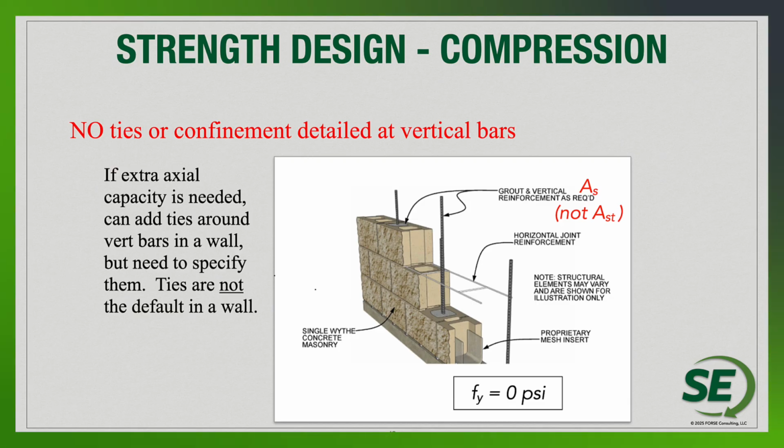One could say you could use, say, a pier design, a flush wall pier design. If you did put some stirrups or put some ties around some reinforcement, you certainly could do that, and you could look at an increased capacity by utilizing the compression in the reinforcement by adding ties and additional reinforcement to that end. But I don't think that is extremely common practice for the design of walls.